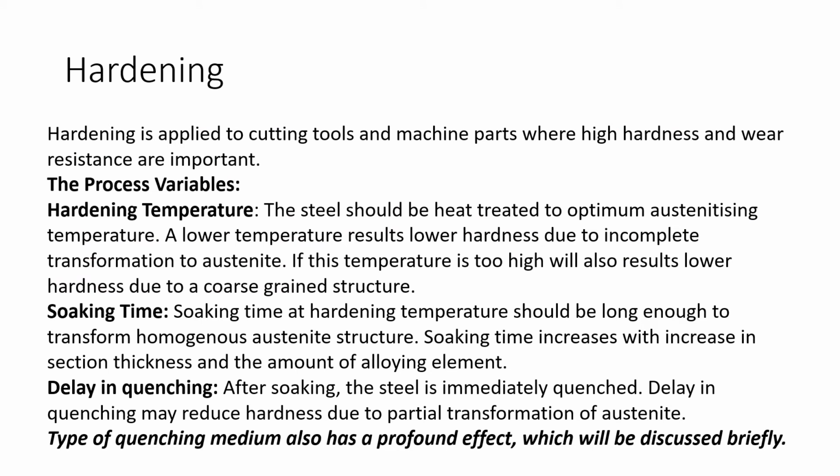Hardening is applied to cutting tools and machine parts where high hardness and wear resistance are important. The process variables are hardening temperature, soaking time, and delay in quenching.